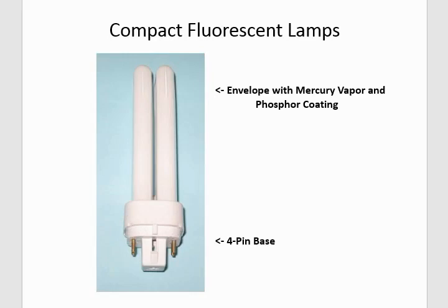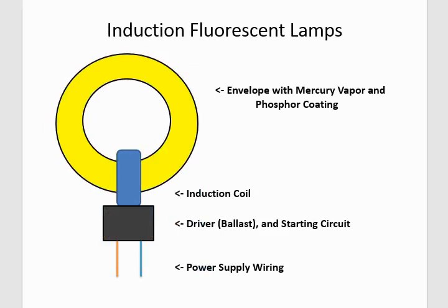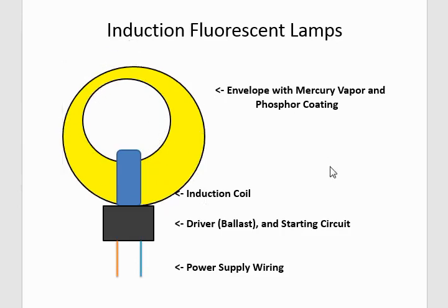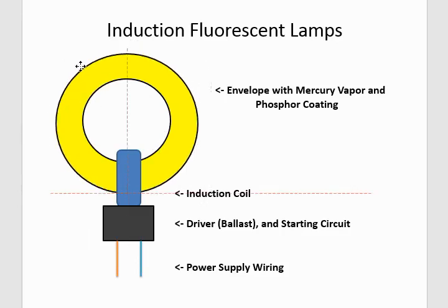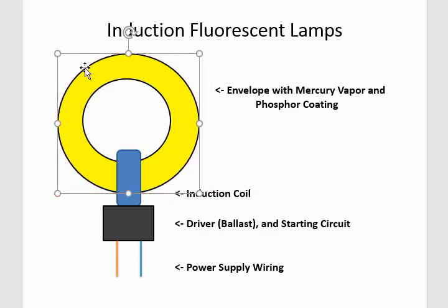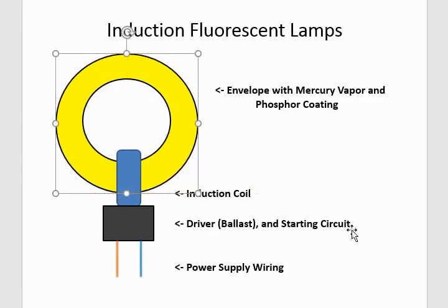on a dimming ballast. Induction fluorescent lamps were used for a bit in street lights and such. It's just a fluorescent lamp, but there are no cathodes, no filaments, no electrodes penetrating this glass envelope. Okay? The mercury vapor inside the tube is excited by, close enough, a coil, and radio frequencies are stuck into the tube and they excite the gas.